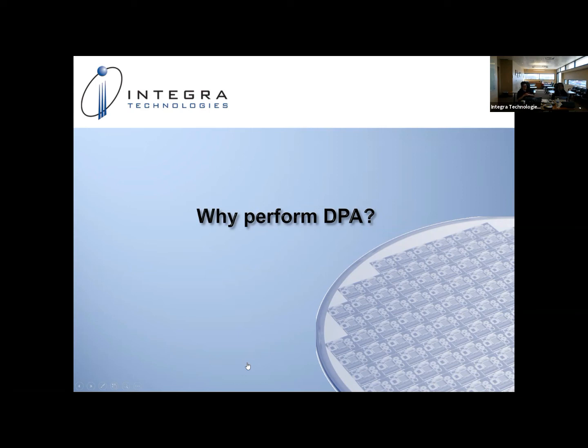No, I'll add to it that there is not a process maturity for copper bond wire amongst all suppliers. The level one suppliers, level one being the ones that make billions of devices a month, versus level 2 and 3, who make maybe a few million pieces a year or thereabouts. What we see is a maturity difference between level 1 and level 2. What we also see is equipment variation.